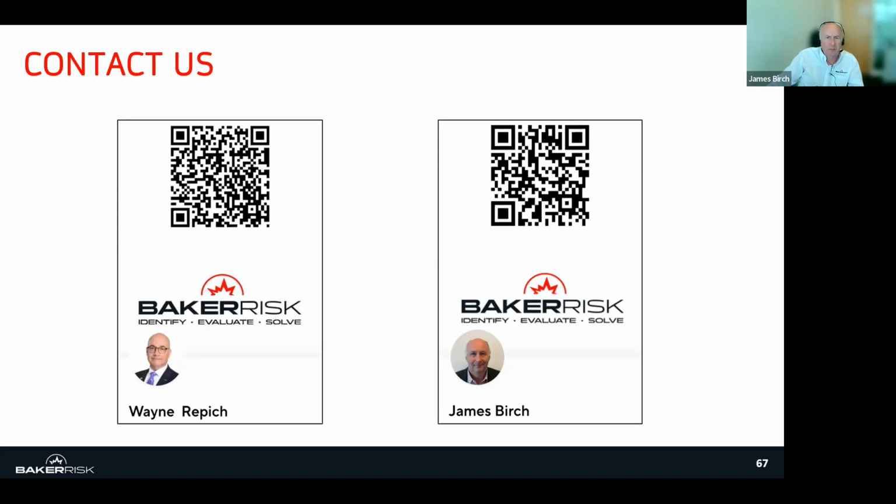And the change might mean we have to shut down. The change might be we have to derate our operations. The change might be we have to bring in additional checks or fit other equipment. You know, the management of change triggers that need to be considered.